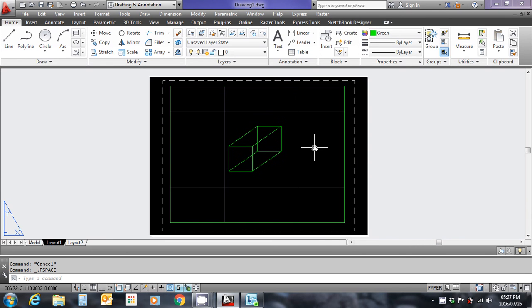Okay, so I'm ready to start dimensioning. Please take note that I'm going to do dimensions in paper space. So that is a methodology which I advise. It just means that if somebody's working in model space, they're not messing up your print layout, and it's easier to control all your dimensions and text heights in paper space. So this is where you're going to print from. It's easy to edit. You don't have to worry about sizes and scaling of text. Everything just looks smart. So the idea is that if you're working in model space, all your layers are on. If you have text of different scales in model space, then it's going to become very, very messy. So we keep our dimensions and text for the paper space environment.